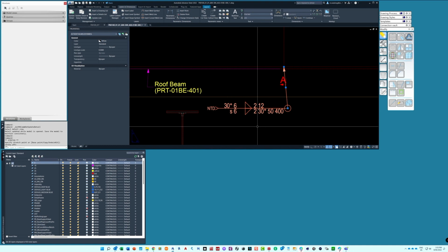And you can see that using the out-of-the-box macro with the block that is used to create the weld symbol, it's really not useful. There's numbers here, but it doesn't match any standard, and it's really difficult to understand what it's actually telling you.